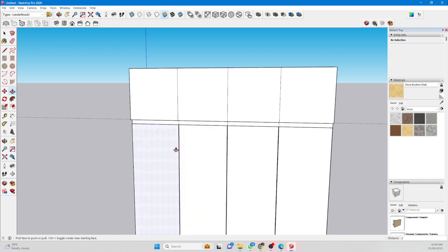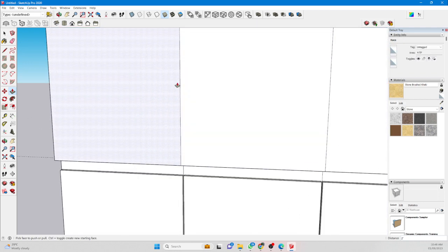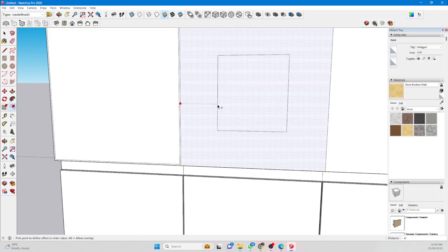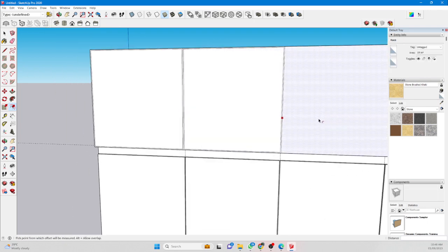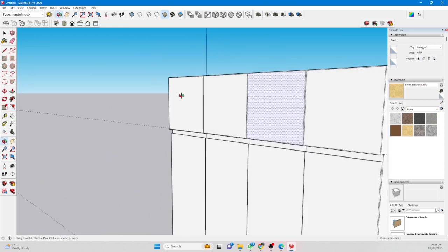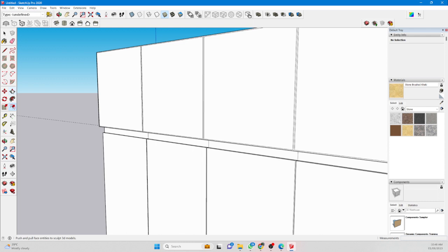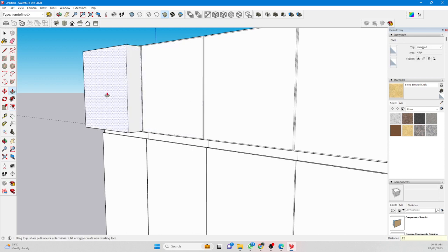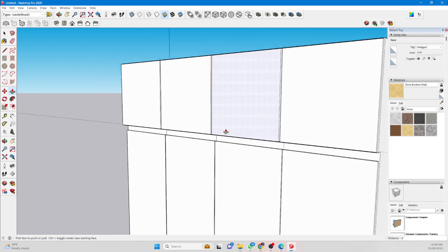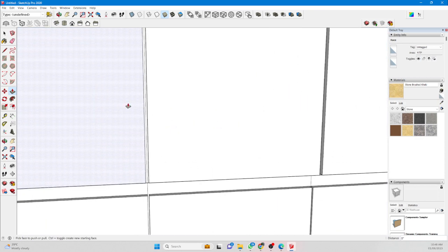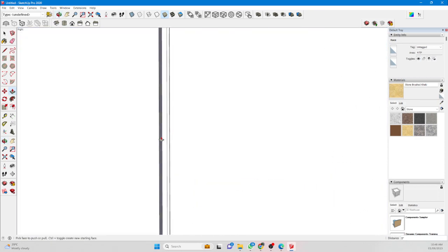So how to create the door right now? How to create the gap? Tell me. You need to go to that option where you did the offset menu, right? Then we'll double click or select it and give 0.2 inches, right? Similarly double click here. Then push pull 0.75 inches, right?